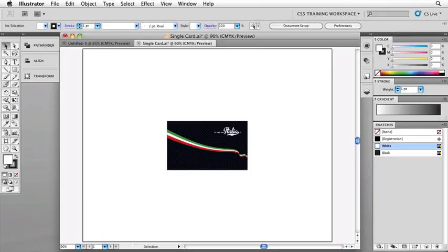So how do we change the actual size of the artboard itself? Well, like I said, there are a few ways to do it, and really the most important thing is the Artboards tool. Now, I pointed this out briefly earlier on. You can see it's over here in the Tools palette. And if I hover over that, you can see it has a simple keyboard shortcut, Shift and O. So that's definitely one you want to remember because we're going to use it a lot moving forward from here.